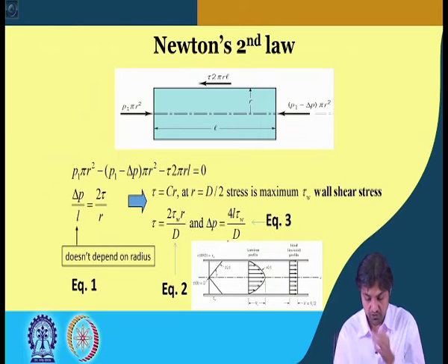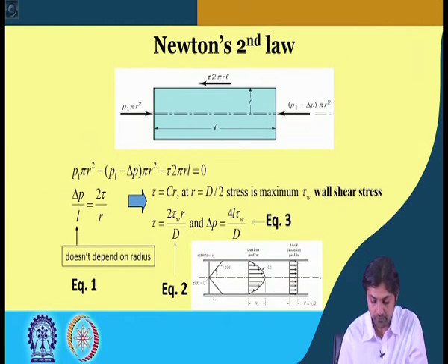So this is the profile, you see. This is the laminar profile for viscous pipe flow, and this is the ideal profile. You see, this is VC. You remember in our laminar and turbulent fluid flow, we derived that the average is VC by 2, the ideal inviscid profile, whereas it goes from 0 to VC.